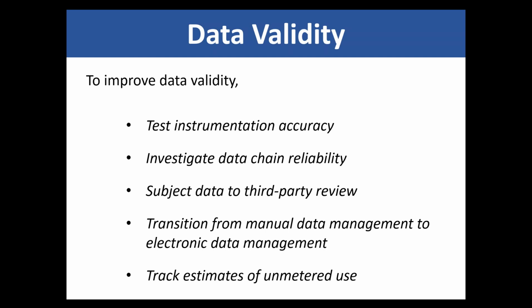Another is to investigate how well your data chain translates volumes from your meter to your 4 to 20 milliamp signal, to your SCADA database, to the historian, to the query that pulls it out of the historian, to the summary function that puts it into your Excel document. There's a lot going on in that data chain process. And if you can investigate from start to finish how that translates your volumes, whether that's a process of fidelity or not, that's helpful for increasing your data scores.